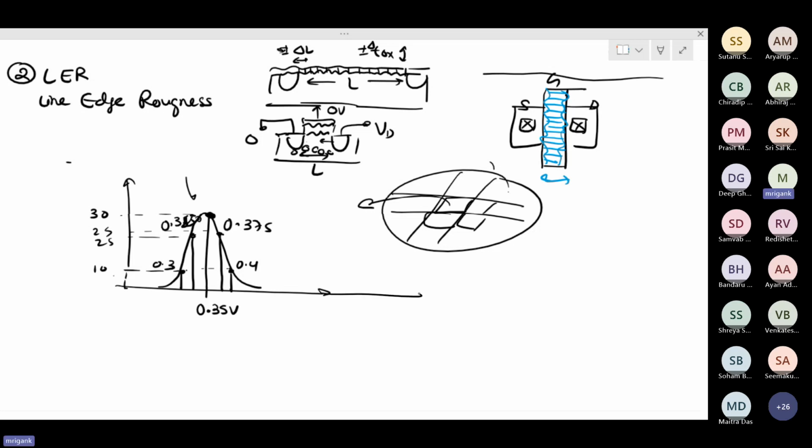Now, suppose this is the VT, threshold voltage of the NMOS. Now, if you had a slow corner, where the MOSFET threshold voltage was more, what will happen to this entire histogram? This is a typical TT. Suppose now I have to plot the same thing for the chip in the fast or slow corner. Slow corner, what will happen?